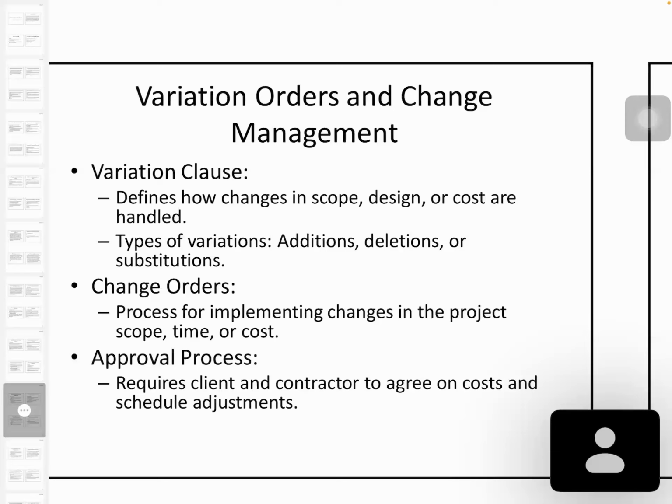We had an incident in one of the projects because the project was earlier designed for a raft foundation. But finally, once you are excavating, the contractor identified that there are loose layers, because it was not identified through the soil investigation.